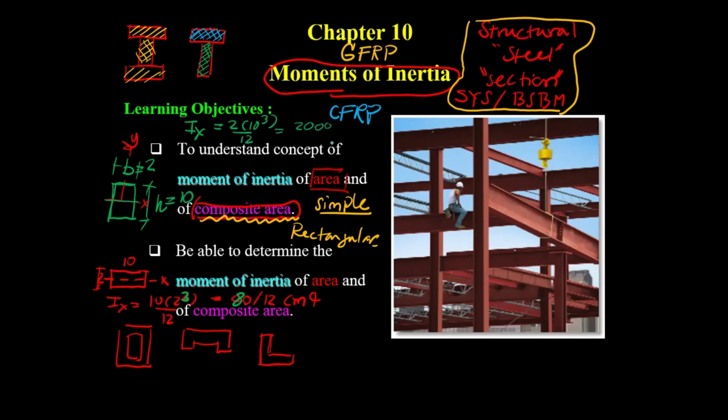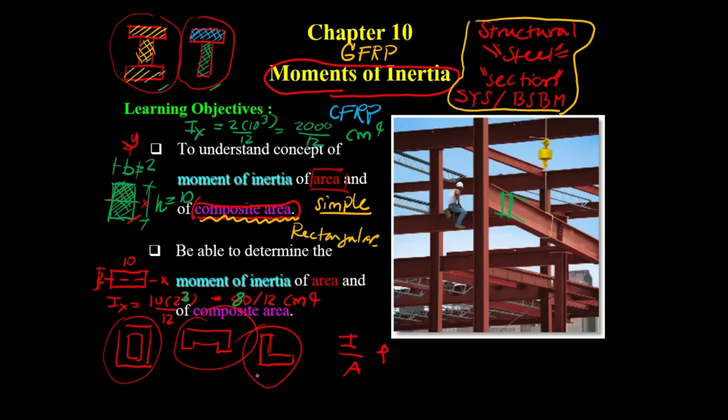This is going to be 2,000 divided by 12. That's a very huge difference. That's why in our practice, you will see the beam put in the position with this kind of rectangular. Now, with this kind of section, for sure, the beam following this kind of engineering section will have a high ratio of I over A, higher than rectangular. So many times we have this kind of section, and again, they are going to be in your final examination.